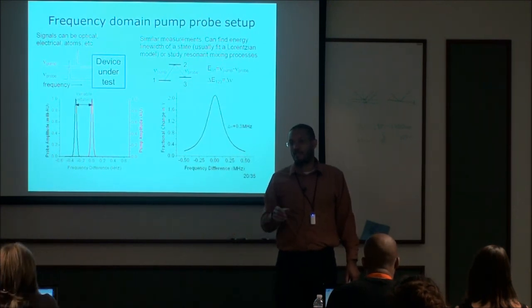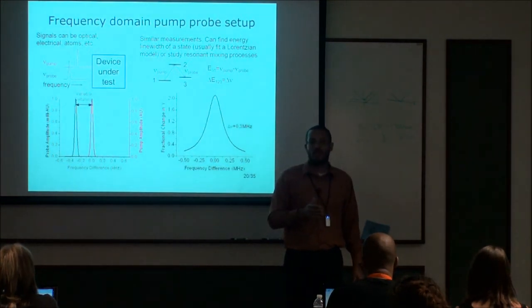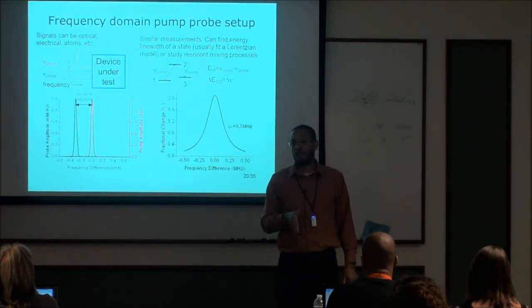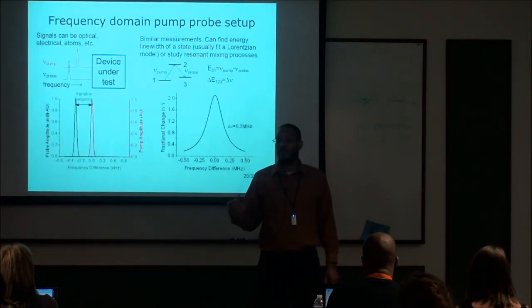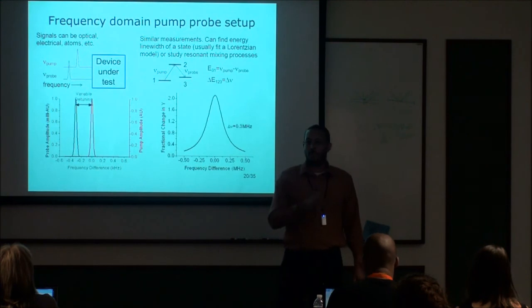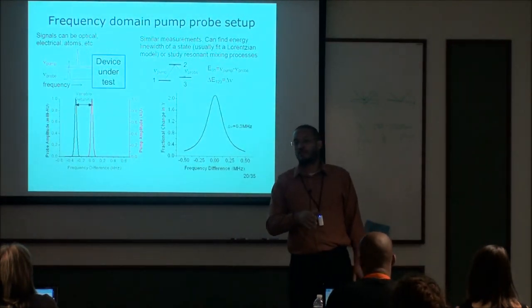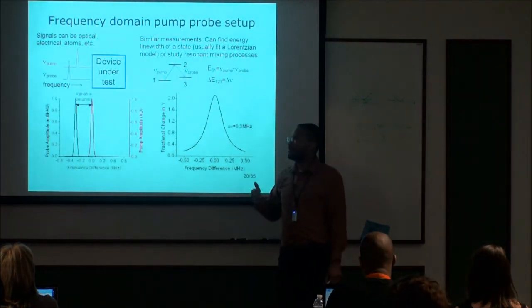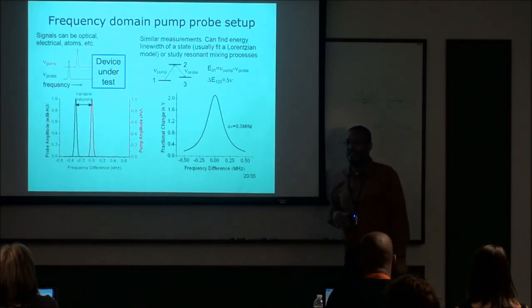And then the resolution that you can get with a monochromator is generally not as good as the resolution you can get with a tunable laser. So with a tunable laser, for example, I can set the laser wavelength accurate to about 1 picometer, whereas if I measure with a monochromator, a typical resolution would be something like 100 picometers. So I usually get better resolution with a tunable laser, and I get all my power at that one frequency rather than wasting it over the band. But tunable lasers are more expensive, so it's a trade-off in terms of cost and how you run your system.